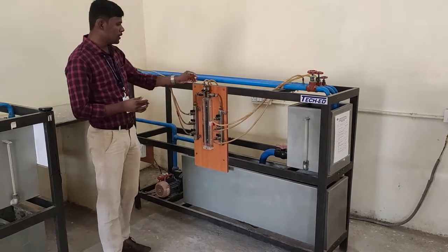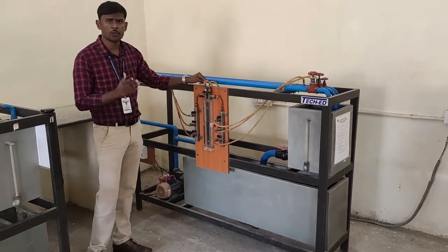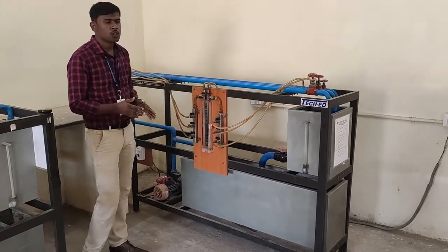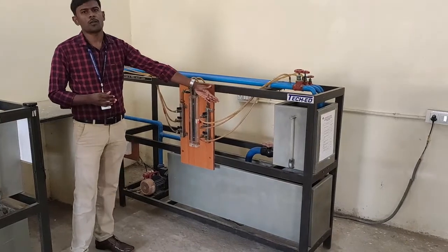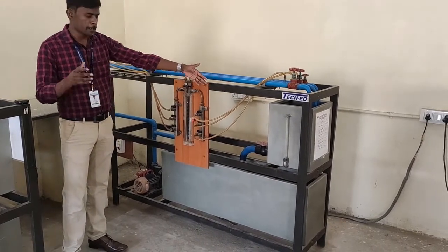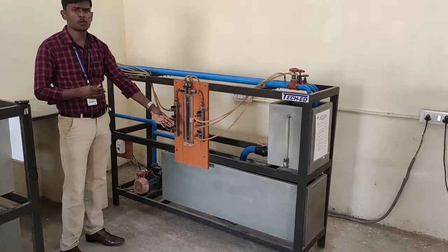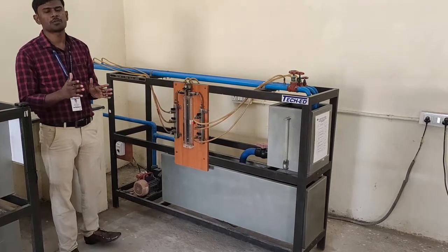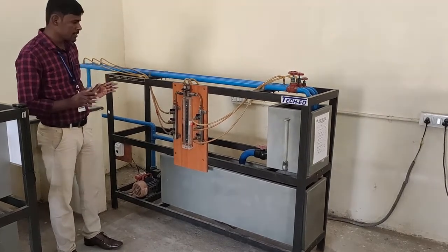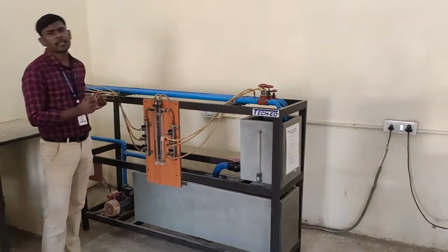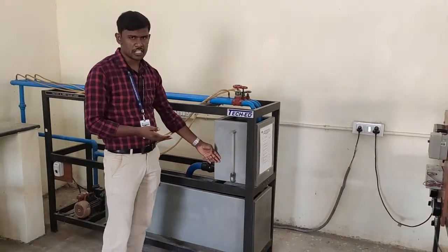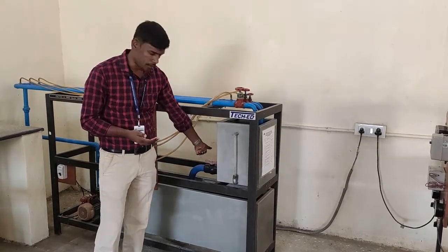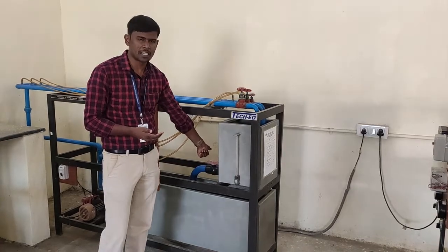If any air voids are there in the manometer, they must be removed before going for the conduction. Then you should open the regulating valve and the corresponding ball valves of the pipe. Then come to the differential manometer and record the left and right limb manometer readings in terms of mercury head. After taking the manometer reading, come to the measuring tank and close the flow valve in the measuring tank.